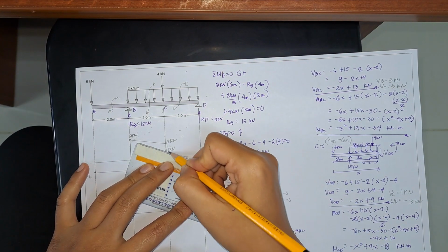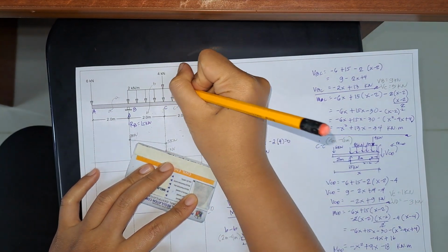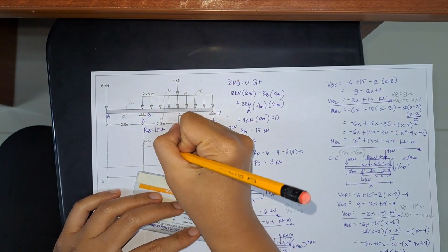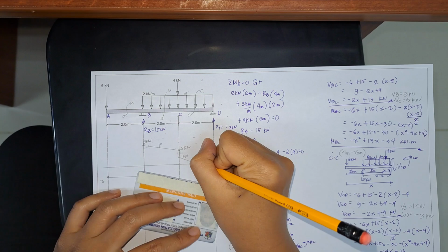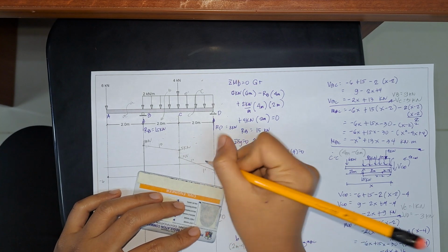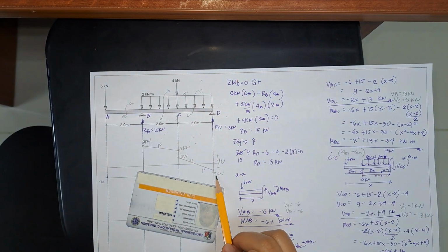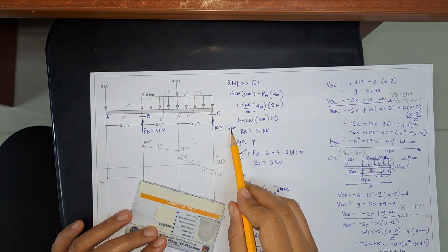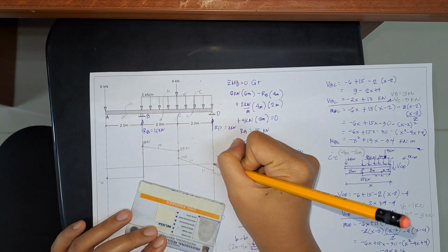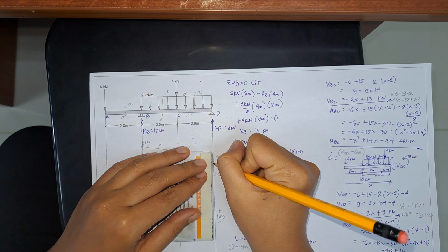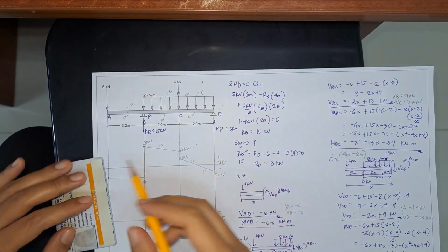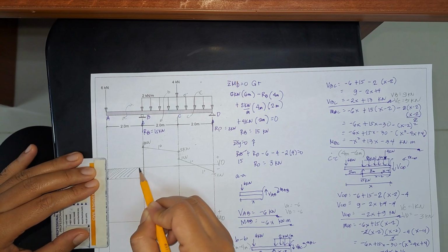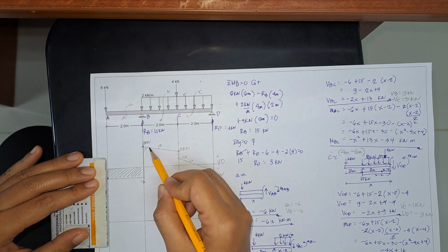So, as you can see here guys, 0 degree yung ating load diagram, 0 degree. So, malamang this is just a straight line, a 1 degree curve. Also, this is a 1 degree curve. Okay? And then, negative 3 po siya. Meron kang force na positive 3. So, negative 3, positive 3 is 0. So, nag-close yung ating shear diagram. Okay? So, ito na po yung ating shear diagram.